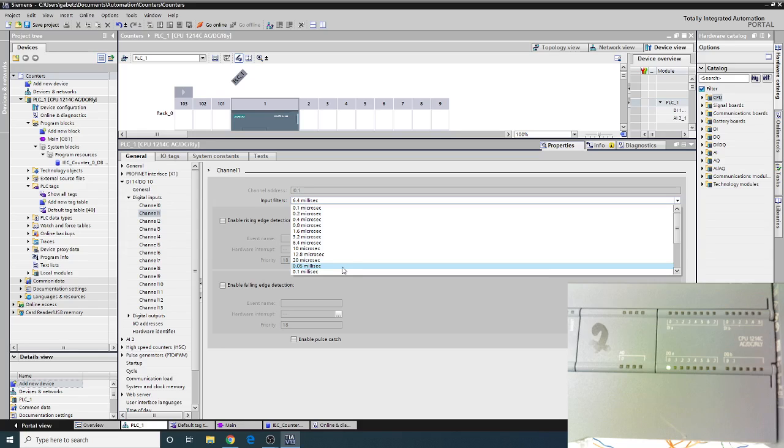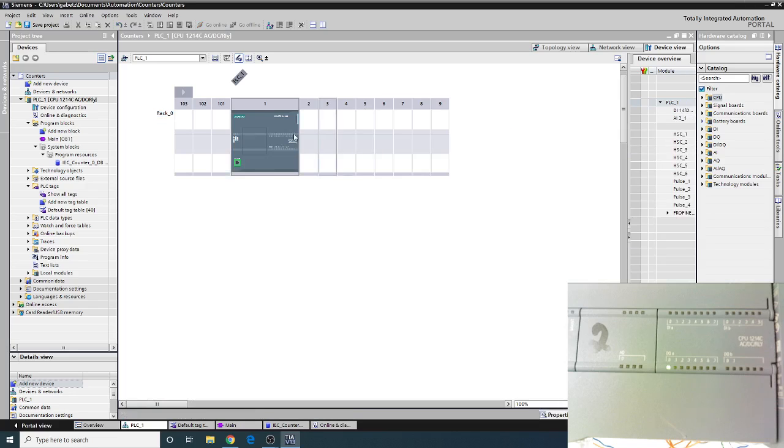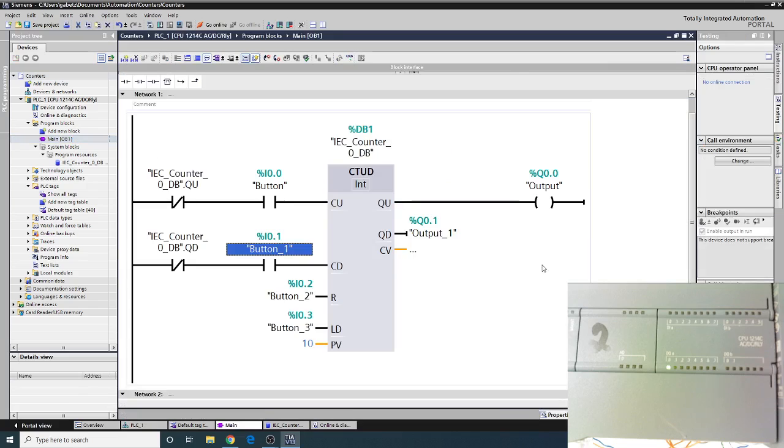So you do have to play with those types of things to make sure those high-speed counters are working correctly with the Siemens PLC that we're currently using, at least. Again, with those dedicated high-speed modules, there's probably some other configurations that you might have to tweak, but just something to take into account. So, counters overall, any big questions?